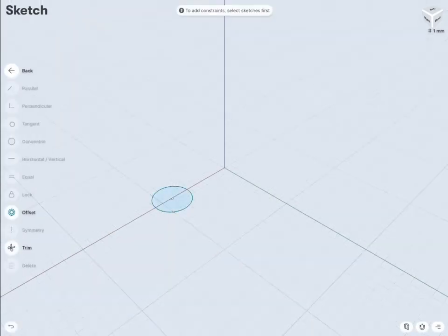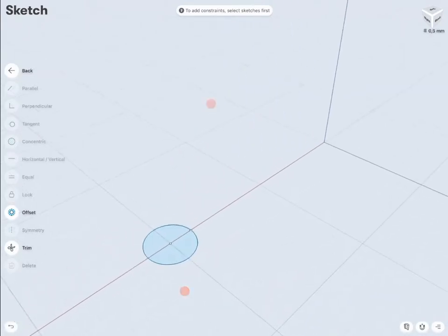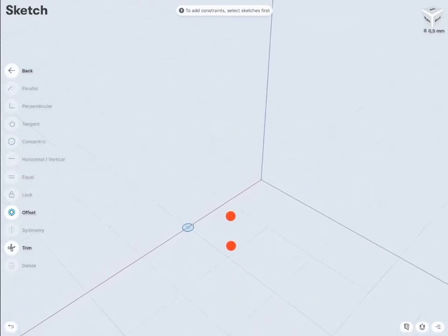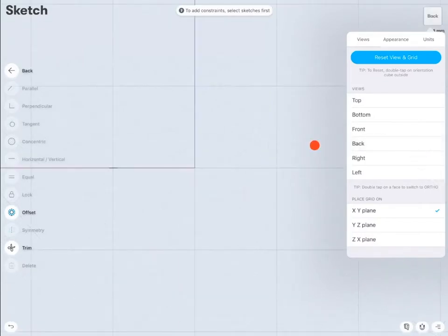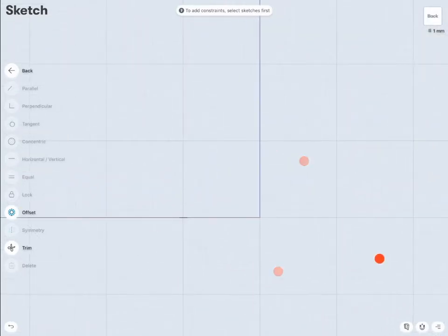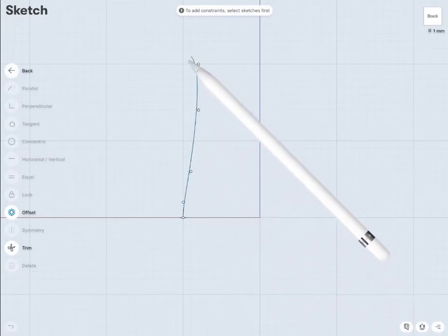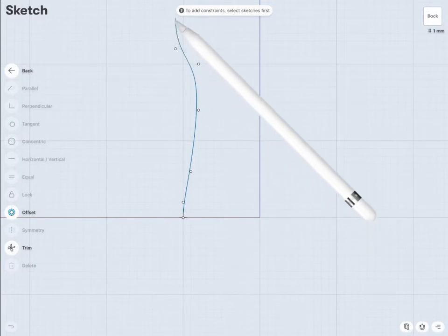At first, we're going to make a circle to create a profile for our base tube. So now, I'm going to use the circle, and I will place it as you see on the axis, and put it around the 0 point. Then I'm going to sketch a spline. This is going to be the base shape. You can always adjust the points as you want.